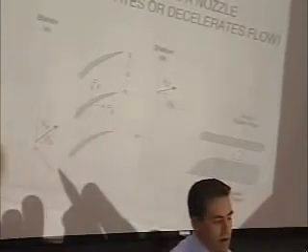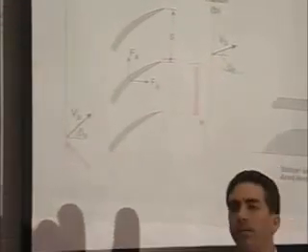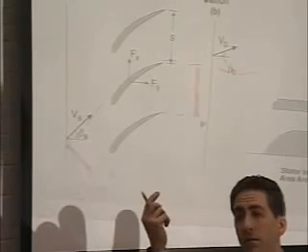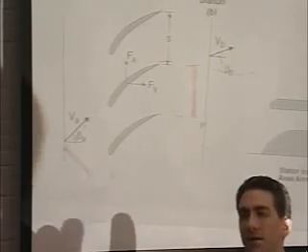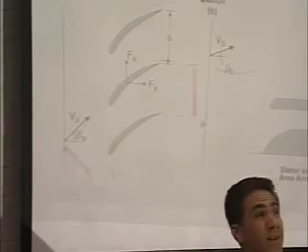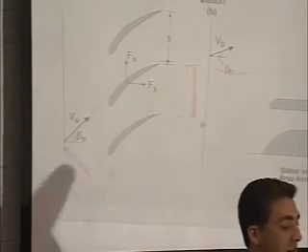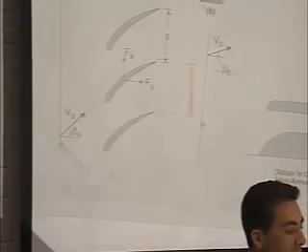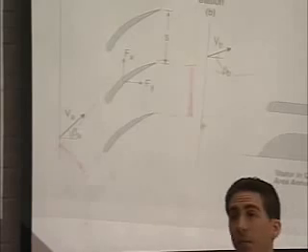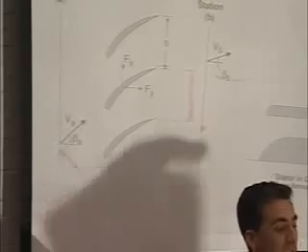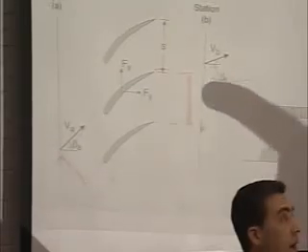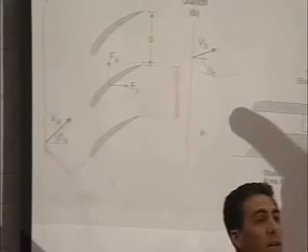So you have a perpendicular distance across this pipe and a perpendicular distance across that pipe coming out, and they're different thickness pipes. So it's just like a nozzle. Right? A nozzle takes internal energy and converts it to kinetic energy. This does the same thing. You've got a small pipe, if you think about it, that gets to be a big pipe. It converts kinetic energy, lower speed flow, to higher internal energy at the exit.